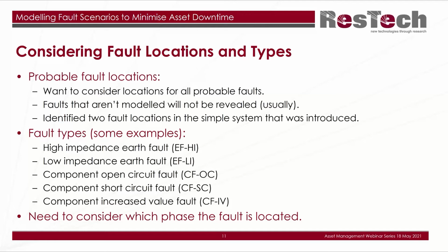And of course, that's in the simplest sense. Of course, you have something like a variable speed drive and you want to probe into that. You have to consider things like faults on the DC bus, whether it's the positive side or negative side of the DC bus as well.